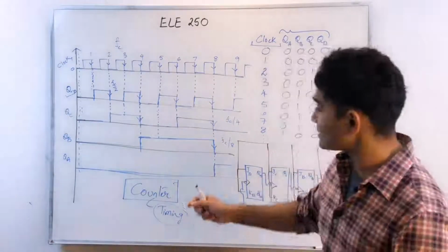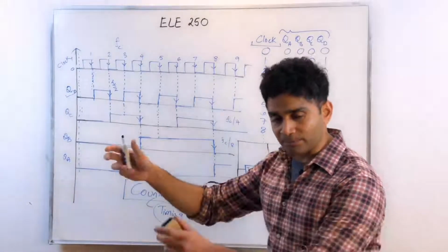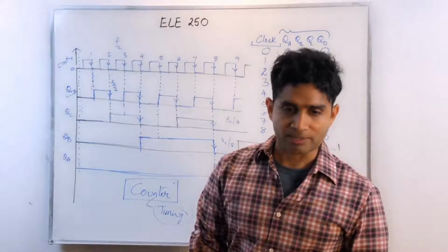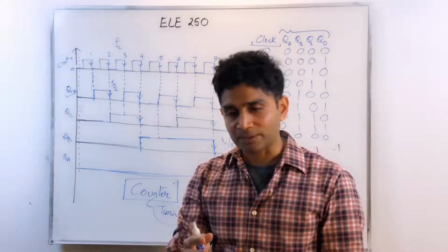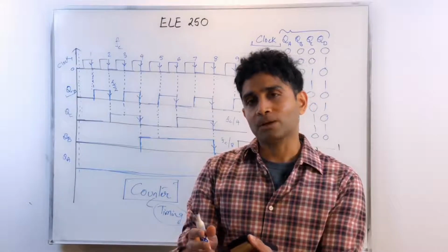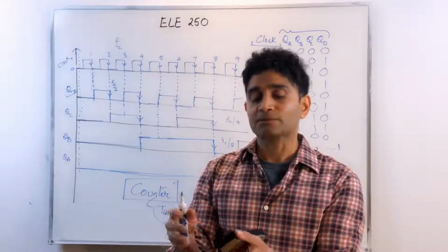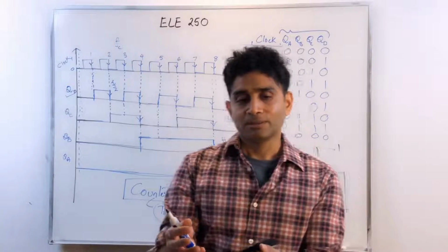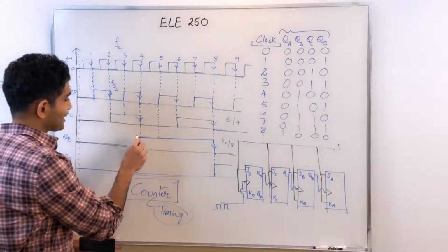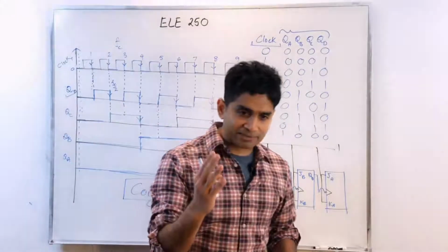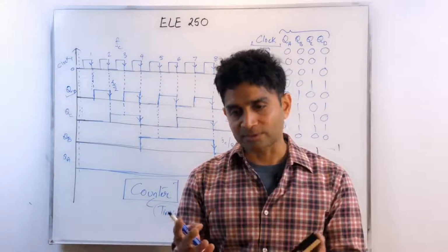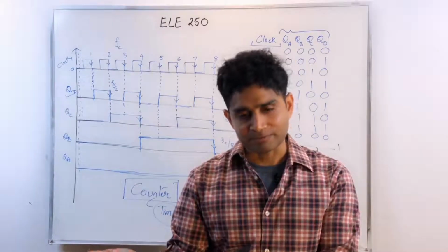So I can use this as a timing signal to indicate that, let's say, a subsystem takes 4 clock cycles to execute an instruction, and then after the instruction is executed, I want to make that system or subsystem inactive. Okay, so I can provide QB as a timing signal, so that it's active for 4 clock cycles, and then after the four clock cycles elapse, that becomes inactive.